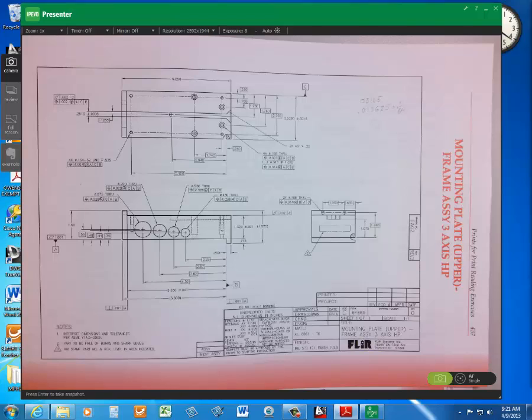Well, listen, when you make a counterbore hole in the machine shop, they're going to use a tool that's got a pilot shank on it, just a smooth bearing surface, and they've already drilled the hole. Then they'll bring the counterbore tool in and cut the counterbore. So they doubled it. They knew what position they needed for controlling the position of the part, and they just doubled the counterbore, you know, just for good measure.